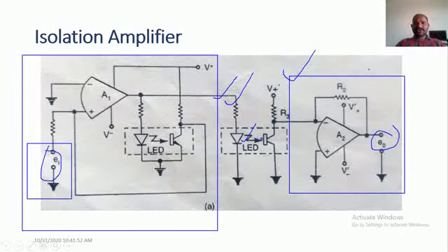Whenever the light is falling, it is read as information. Whenever the light is off, then it is in the off mode. Now we don't have any physical connection between the LED and the phototransistor, so it is acting as a signal coupler to couple the measured information with the output device.